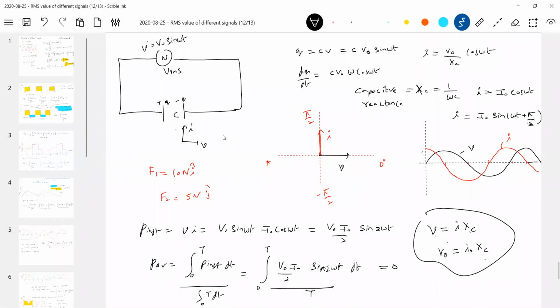The capacitor makes current lead voltage, and it will not consume any work. If you send the same AC signal across a resistor, it will make the current be in phase with the voltage, and it will dissipate power. The capacitor is bringing some changes without consuming any power. Are you able to understand this? What changes? It is making current lead voltage. Is it spending any energy for that operation? No. It's just a storing element.